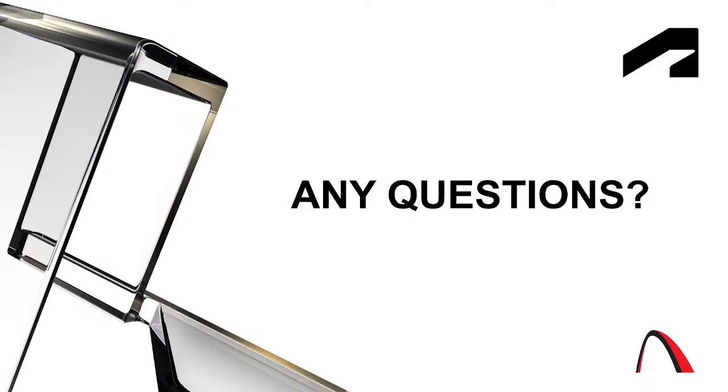So I think even if you have a beam around the edges of the slab, you can simply add it in. How it would change is you would have the spring elements between the beam, so it will be the beam and the spring elements on the edges, and then inside the slab you will have the spring elements connected to the slab. So that's how the difference would be.